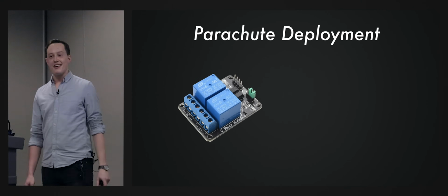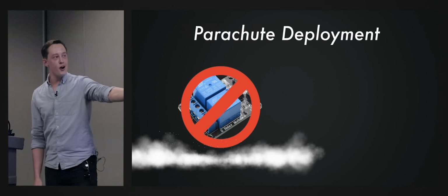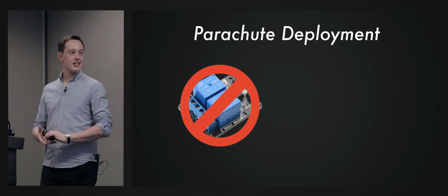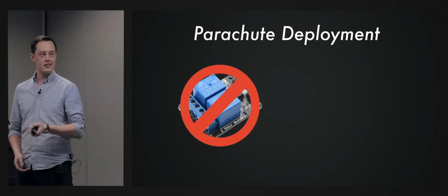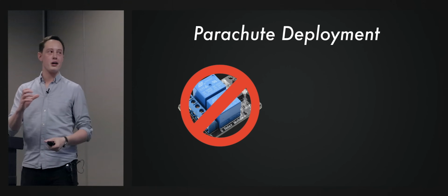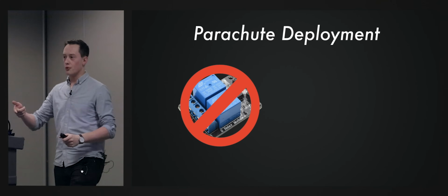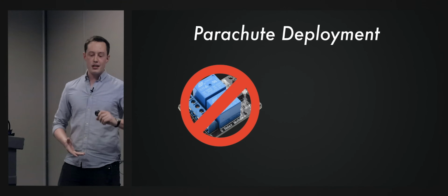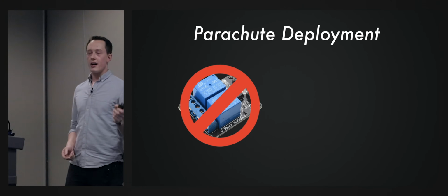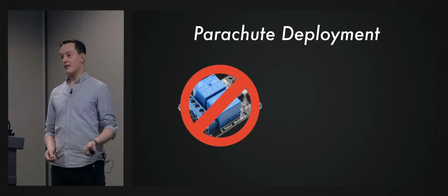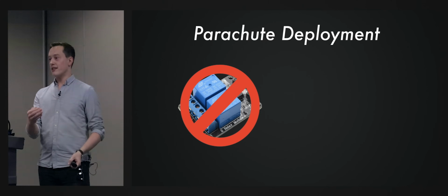Can you use a relay on a rocket? Ready? No, do not do it. Don't use a relay on a rocket. Why not? Because it is an electromechanical device, which means it is a small physical switch inside, which is triggered by a solenoid or a little magnetic core, right? And so when you have a high vibration or a high shock event on a rocket, if you use a relay, you are at risk of triggering whatever's on the other end of that relay, right?